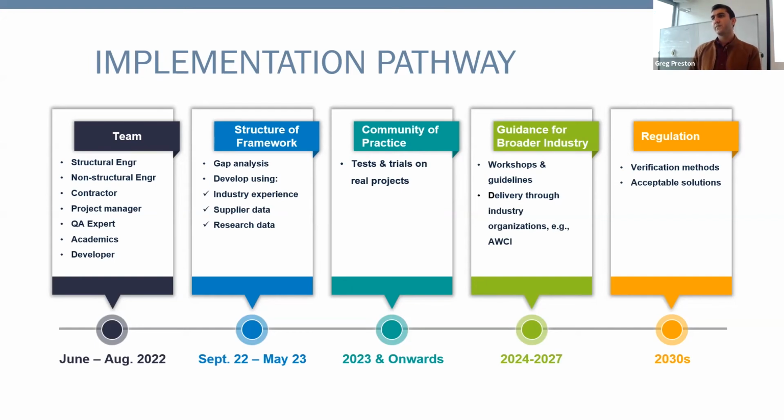So I think a really important component here is to look at the interface between existing building services and new building services, and their strategy of restraining them. If we restrain new parts but have all parts attached to them that are not restrained to the same accelerations or calculations or even standards, because we're going back 50 years, 60 years, etc.